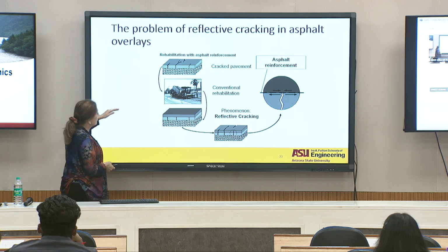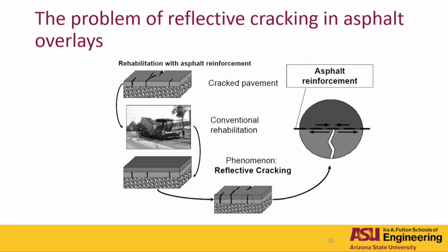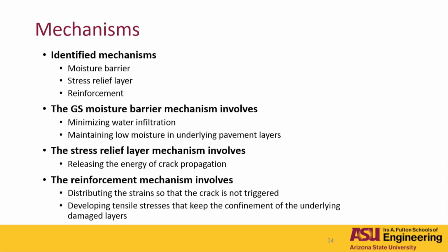So again, you've got all this cracked pavement that you need to rehabilitate. Before you put this one down, you create the asphalt reinforcement right in the middle, right? So you avoid all these cracks just propagating upwards. Okay.